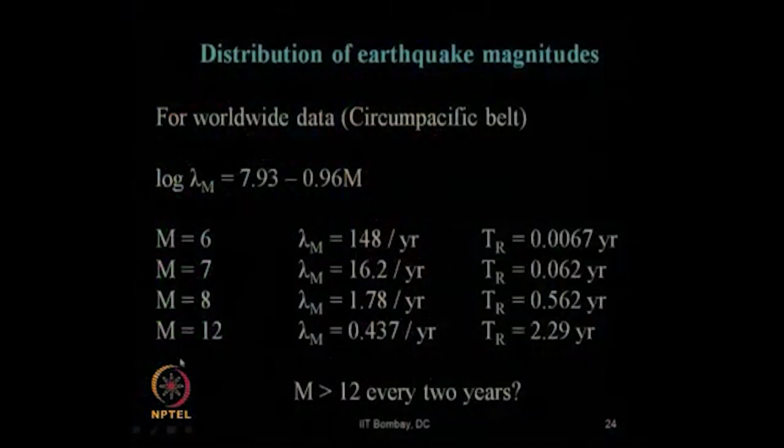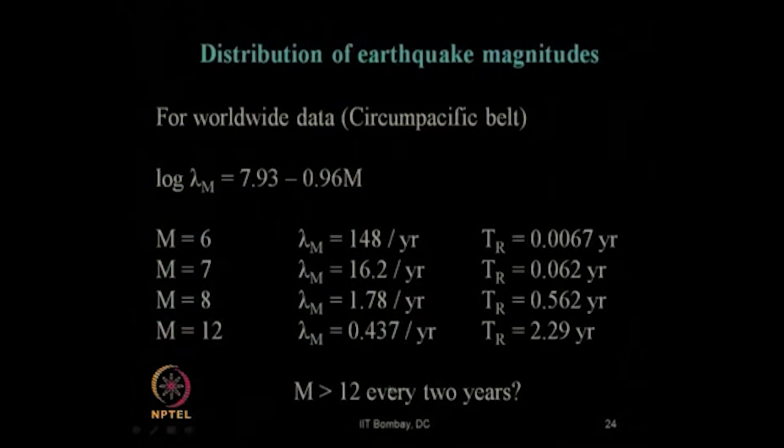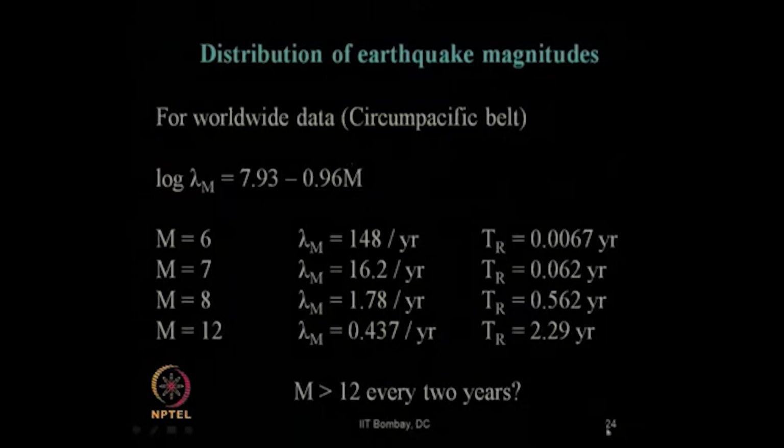Now, we also have to select a maximum value, because otherwise it will give us unrealistic data, which has no meaning in the calculation of probabilistic seismic hazard or recurrence period. Even if I use M20, which will never occur, it will still give some value.